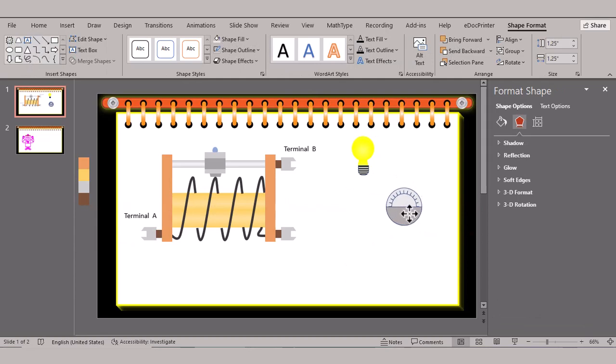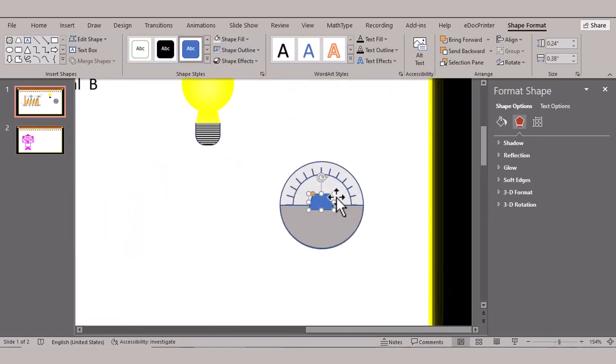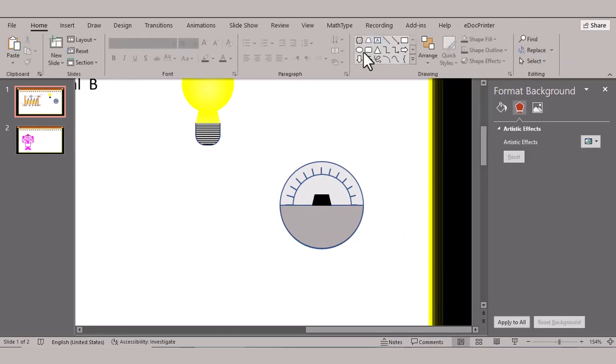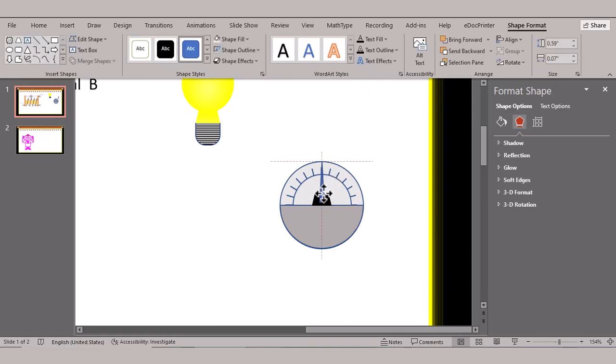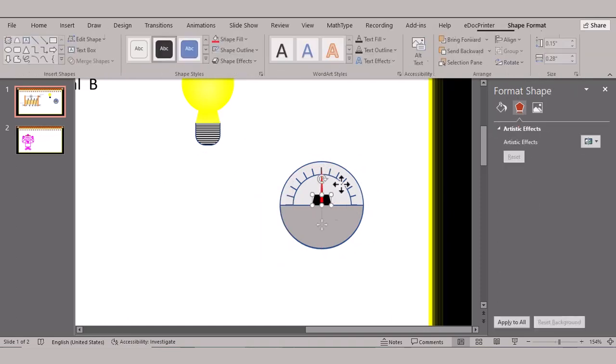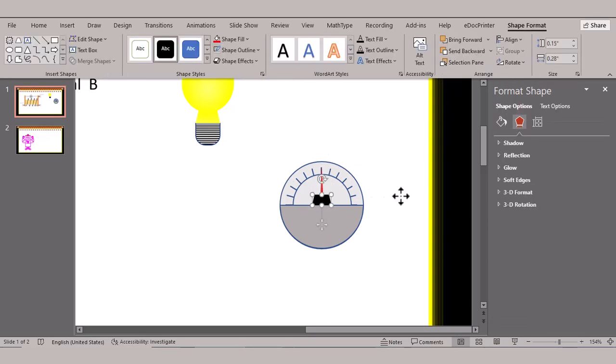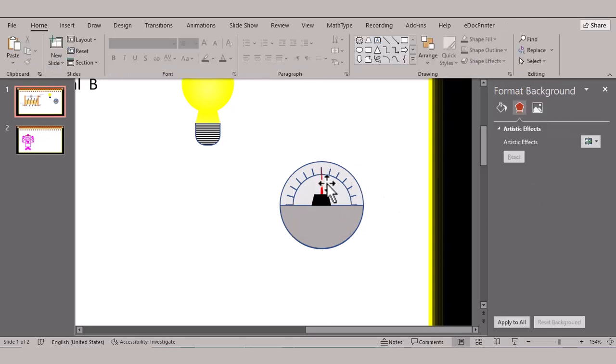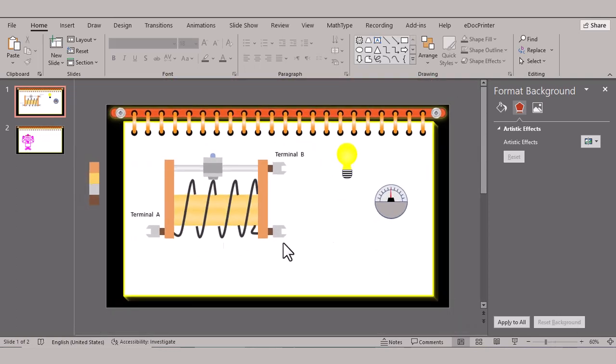For direct measurement, the ammeter is connected in series with the circuit in which the current is to be measured. An ammeter usually has low resistance so that it does not cause a significant voltage drop in the circuit being measured. Instruments used to measure smaller currents, in the milliampere or microampere range, are designated as milliammeters or microammeters. Early ammeters were laboratory instruments that relied on the Earth's magnetic field for operation. By the late 19th century, improved instruments were designed which could be mounted in any position and allowed accurate measurements in electric power systems. It is generally represented by letter A in a circuit.